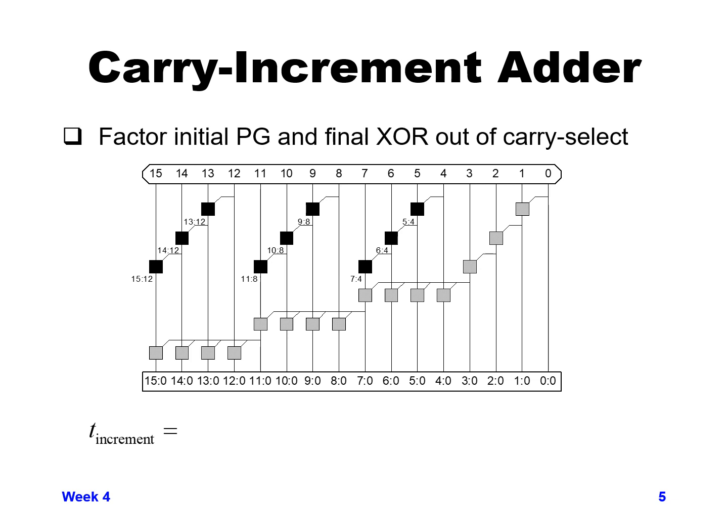So here you can see, if we start in the upper left as normal, we ripple through the first three bits, and then we have a value from bit 3 that's used in common for bits 4 through 7. So we go through the first 3, we skip over to bit 7, we go down and skip over to bit 11, and then the final delay is going to be bits 12 through 15 all get calculated at the same time.